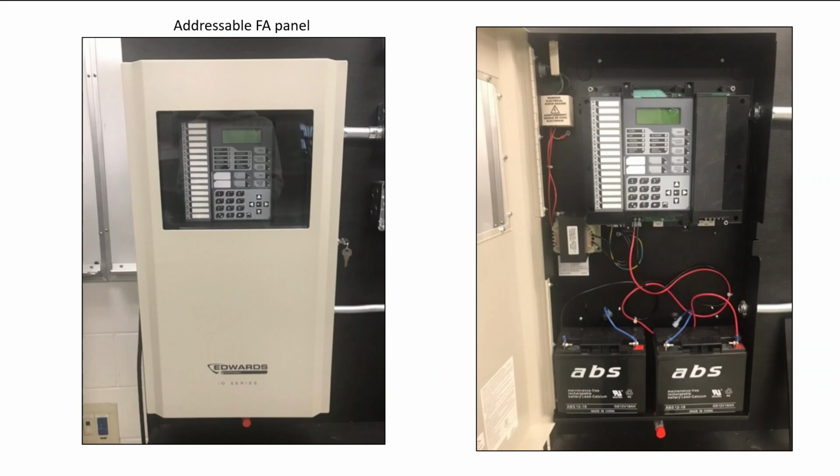This is an example of an addressable fire alarm panel, and you'll notice it has all of the same requirements as what we saw in a conventional, as in a 120 volt connection coming in the top, which then supplies a 120 to 24 volt transformer and then goes off to a full wave bridge rectifier and some batteries in the base. But there's a lot more buttons. There's a keypad here and buttons to navigate a menu, and that's because an addressable fire alarm system will most often require programming.